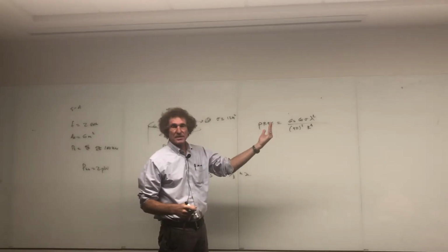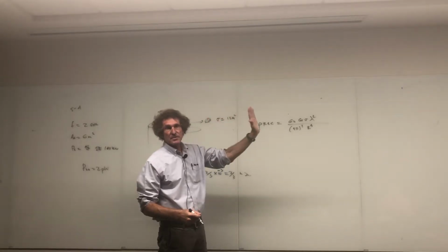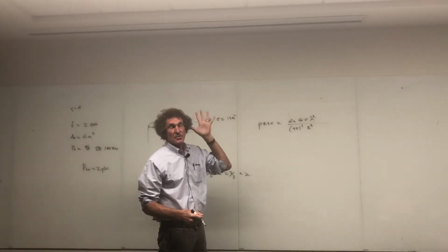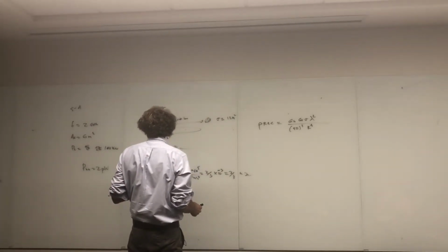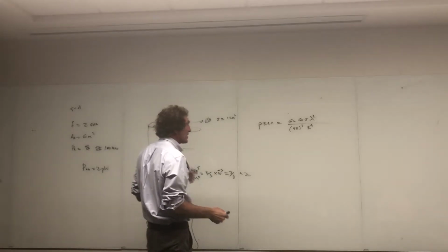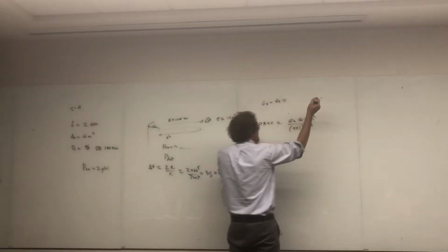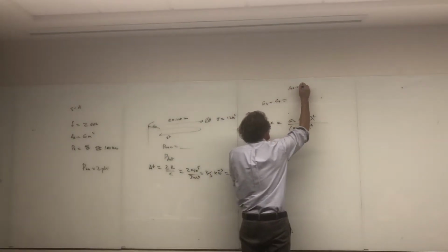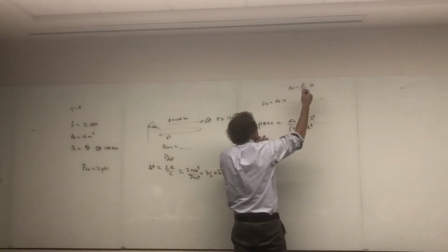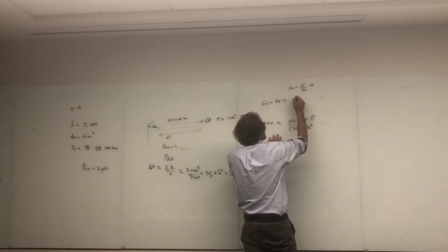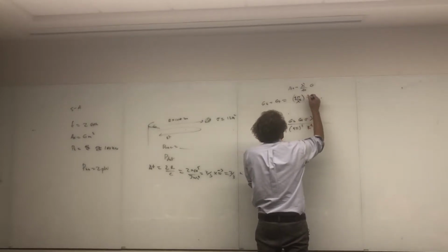It takes care of the incident power density on the target, the amount of energy scattered, and the 1 over r falloff as the power is scattered back to the transmitter. Here, the receiver and the transmitter have the same effective area, so gain of the transmitter is gain of the receiver. If you remember, the effective area is lambda squared over 4 pi times gain in general, so gain is equal to 4 pi over lambda squared times the area. Do you all follow me on that?